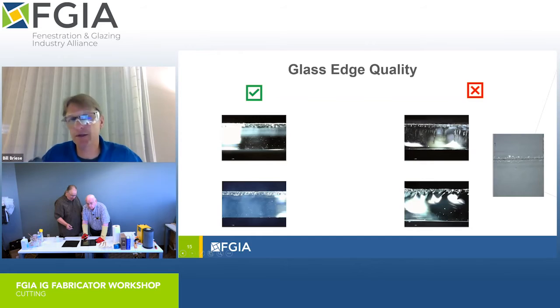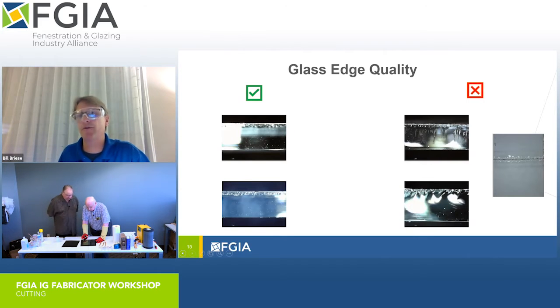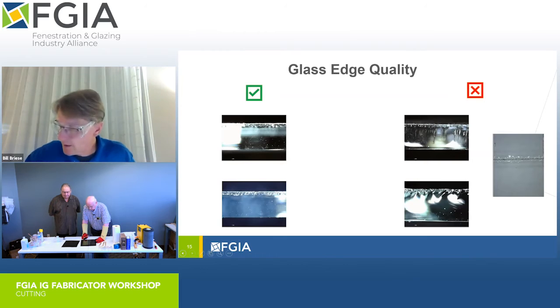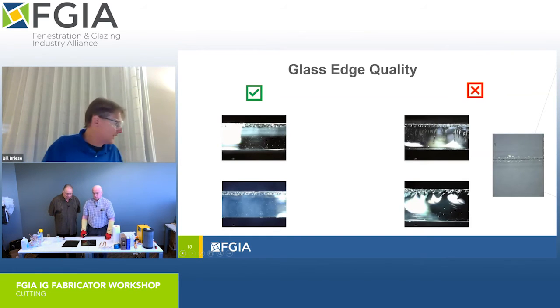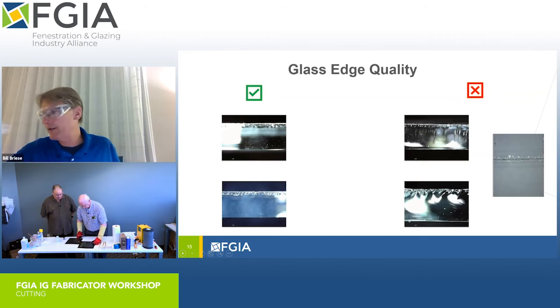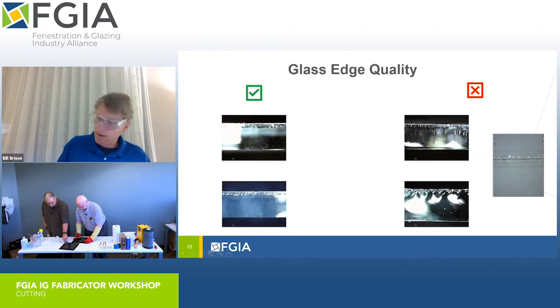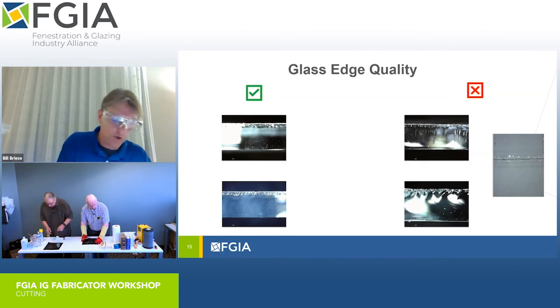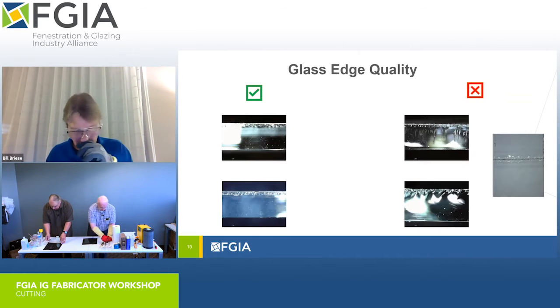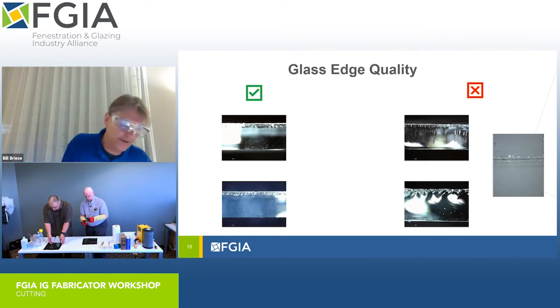So can you feel a distinct difference between the 127, 135, 145, and 155? Yes. Big, huge difference. Mind you, we're working on 4mm glass, and it might behave a little different on other glasses. So now that you've got the lay of the land on that, get a fresh piece of glass and make a score line with a 127, maybe an inch or inch and a half from the edge of the glass.